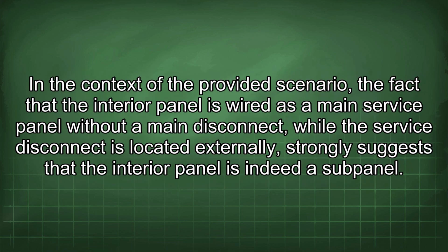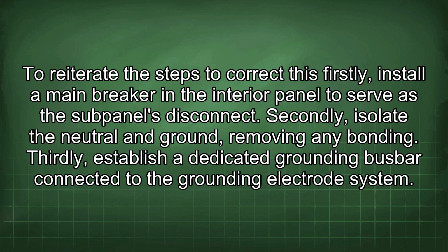In the context of the provided scenario, the fact that the interior panel is wired as a main service panel without a main disconnect, while the service disconnect is located externally, strongly suggests that the interior panel is indeed a subpanel.